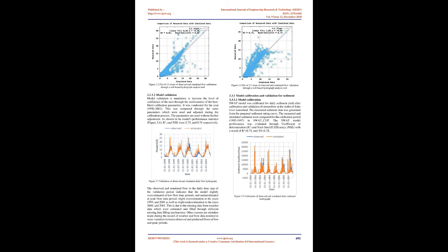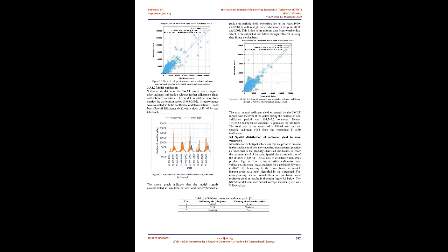3.2.1.2 Model Validation. Model validation is mandatory to increase the level of confidence of the user through the confirmation of the best fitted calibration parameters. It was conducted for the year 1998 to 2002. This was computed through the same parameters which were used and adjusted during the calibration process. The parameters are used without further adjustment. As shown in the model's performance statistics, Figure 3.4, R2 and NSE were 0.75 and 0.74 respectively.